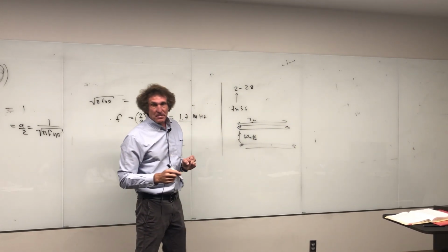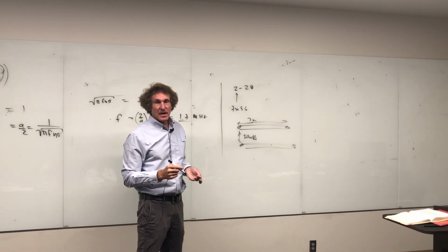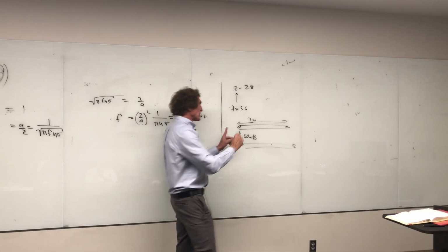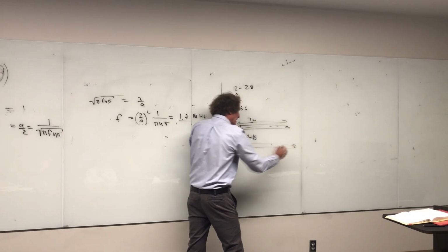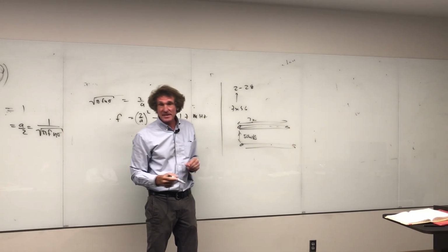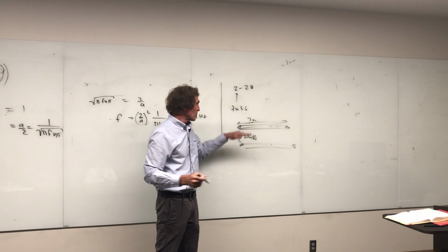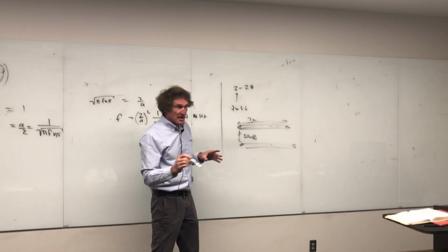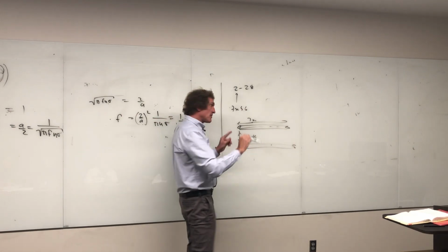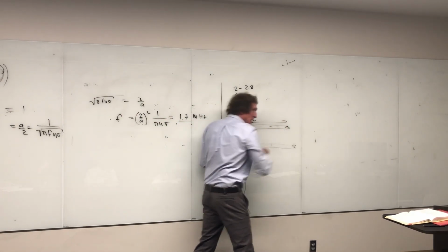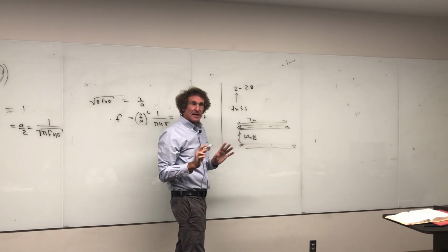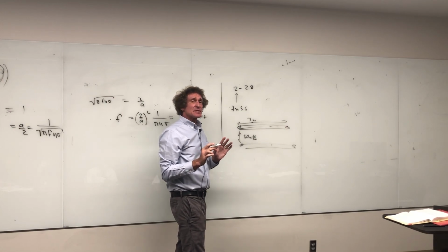All right, for this problem, he wants the resistance. When they say resistance of a piece of wire like this, hear me now. They want the resistance of current going down and coming back. So the resistance of basically twice one of the wires. Understand? That's what they want. They're not in parallel, it's in series, because when we deliver power, it goes down one, comes back the other. So the net resistance is twice that of one of these. Got that, everybody? You got to understand what's going on. Now he wants the AC resistance of this, is that right?